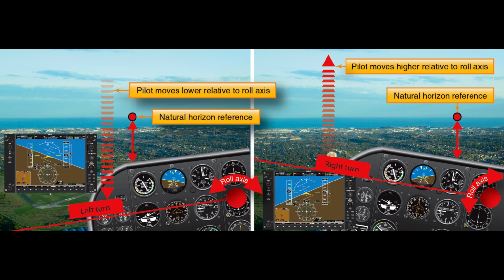The pilot should know the engine power settings, natural horizon pitch attitudes, and flight instrument indications that produce the following types of climb. 1. Normal climb, performed at an airspeed recommended by the airplane manufacturer. Normal climb speed is generally higher than the airplane's best rate of climb. The additional airspeed provides for better engine cooling, greater control authority, and better visibility over the nose of the airplane. Normal climb is sometimes referred to as cruise climb.